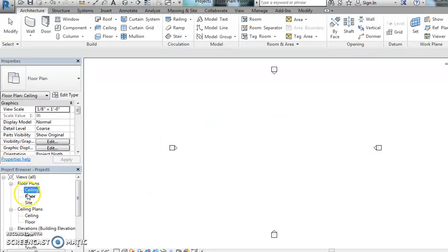You're going to use this project browser a lot. When you're doing your two-dimensional view from the top, you're going to be working on your floor plan. You're also going to use this elevations view every now and again, and I usually just use east. It's the first one there. That's how you set the height of your ceilings.